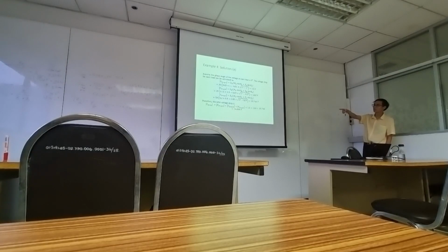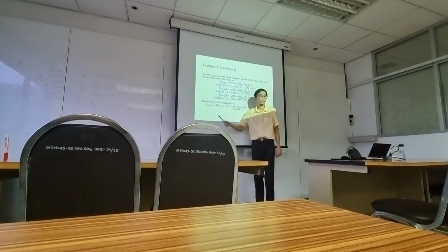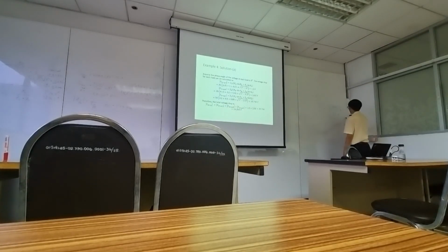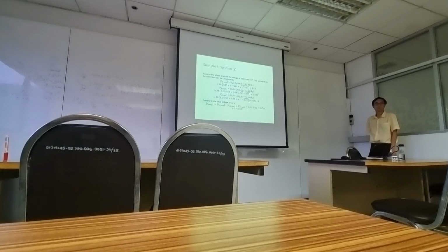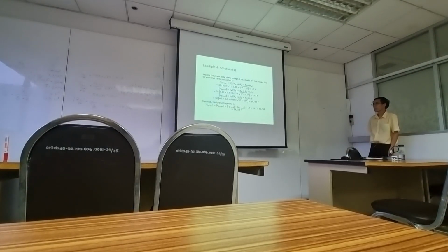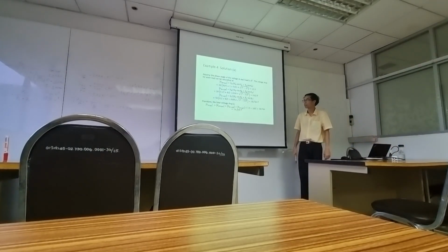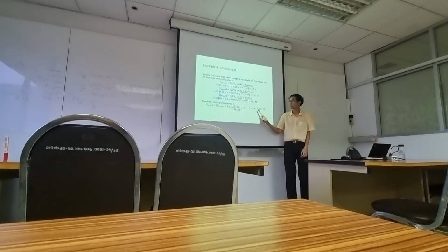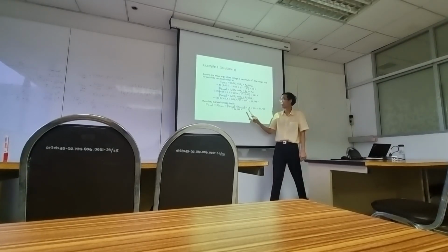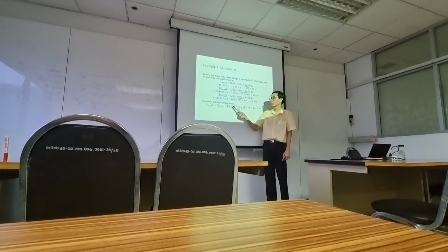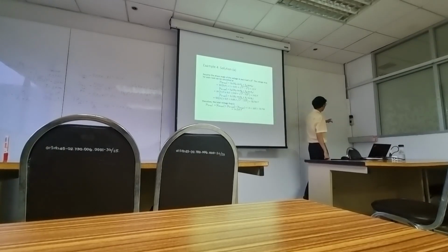The location where we measure the voltage drop would be at the feeder end, at C, because at location C it includes the effect from A, B, and C.